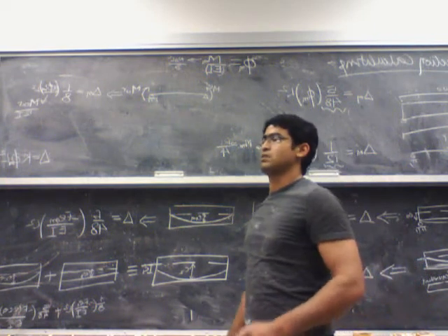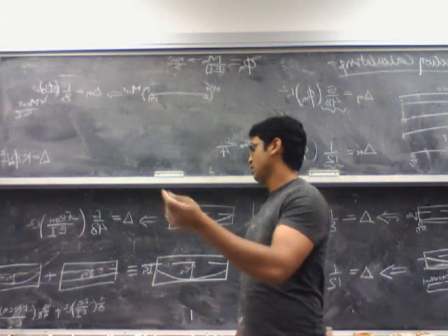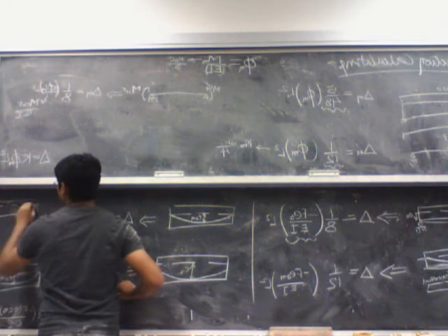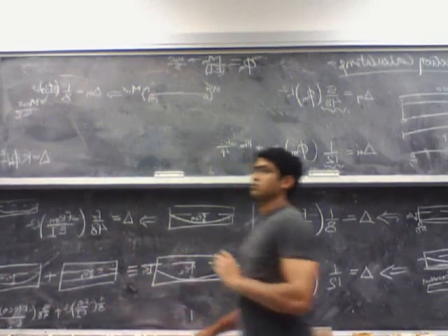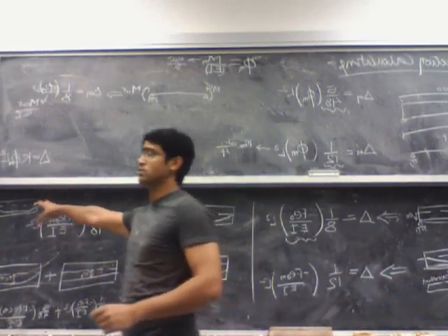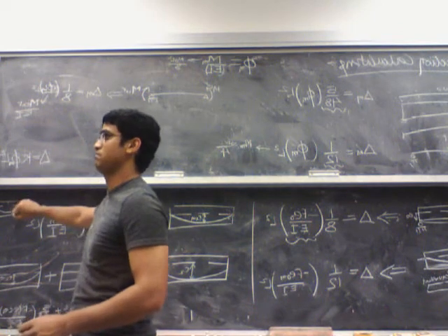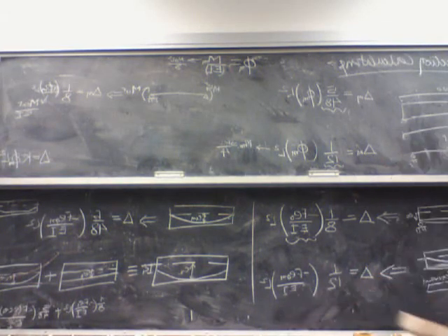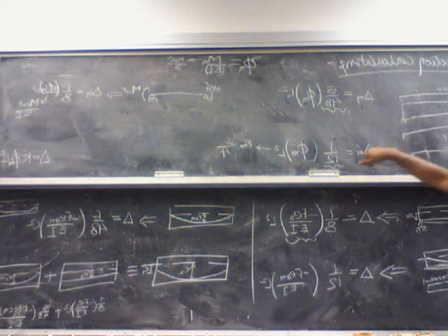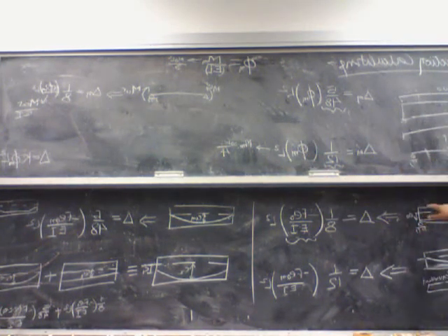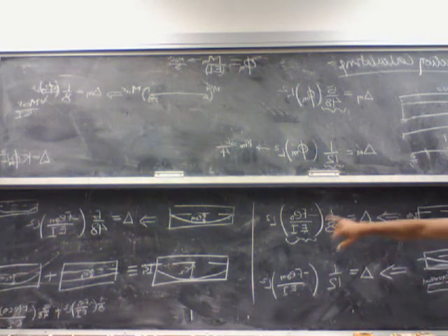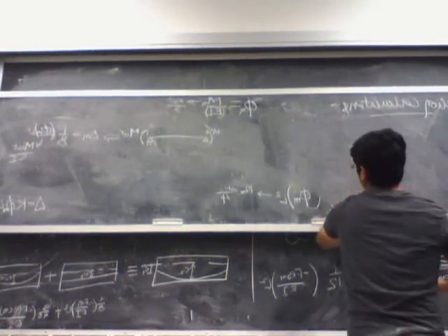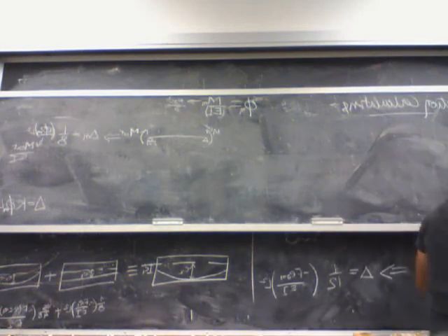Okay. So I think for the deflection calculation in the lecture, I derived the equation for a case where the tendon profile was something like this. So even in this case, actually in this case you are not using the method of superposition. In this case you are using the moment area method. Okay. So now what we have is a formula for deflection due to the external loads, depending on what kind of loads I have. And I have a formula for the deflection due to the prestressing forces, depending on what kind of profile I have. So now comes the total deflection.